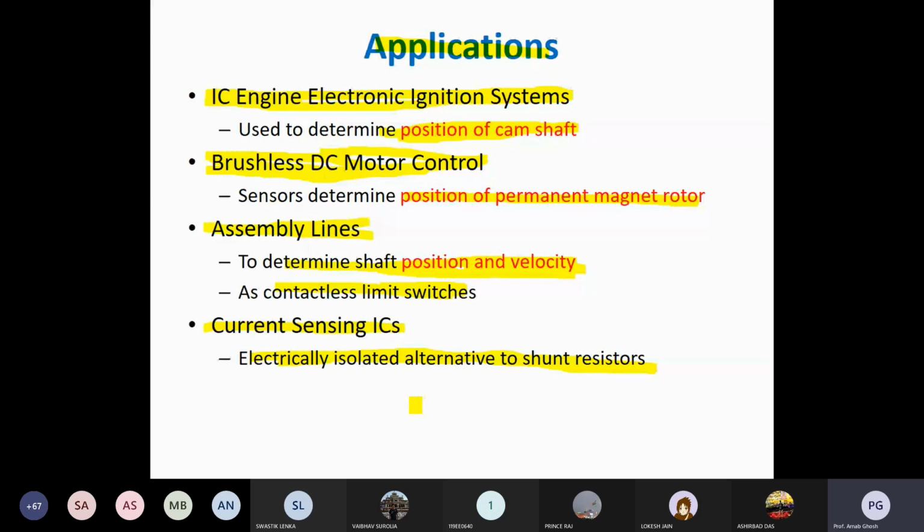So who is responsible for that isolation? Those types of sensors, or you can say transducers, are responsible for maintaining the isolation. It's a magnetic isolation. If optical sensors are there, then optical isolation will be there. Photosensors are all examples of optical isolation. Isolation is normally done for isolating the grounds. So that's the basic motivation.